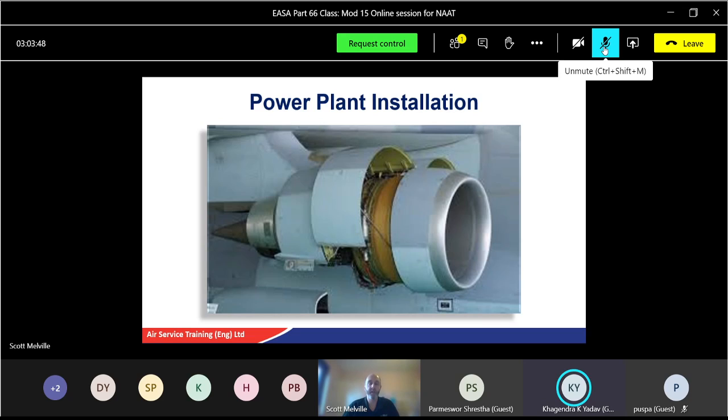It's not that though. A scavenge pump, yes, we have a scavenge pump. MCD, there we go. What's an MCD? Magnetic chip detector, which will detect the small particles. Good. Yep, that's right. So a fuzz burner is an electrical version of an MCD.